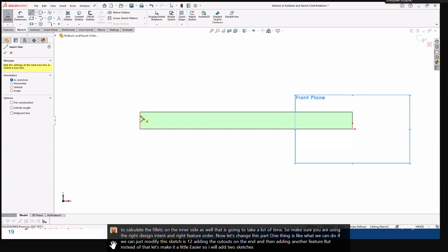Click on this. I have the selection toolbar set to off. If you have it on, you can click on the edge and SolidWorks will help you or prompt you for whatever edges you want to select. So we'll select the desired edges, click OK. We'll do the same thing for the fillet too. So instead of this edge, we can simply select these three faces. So we have